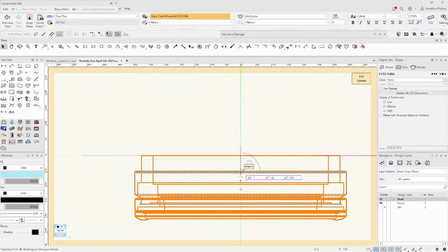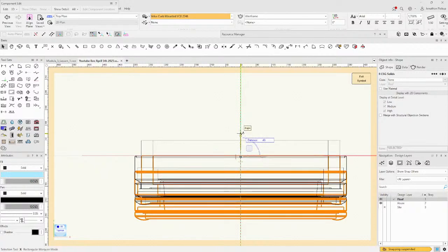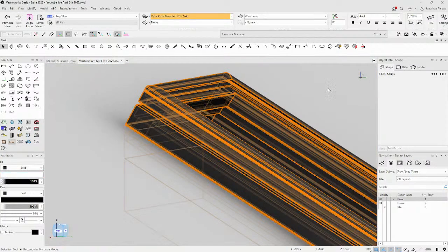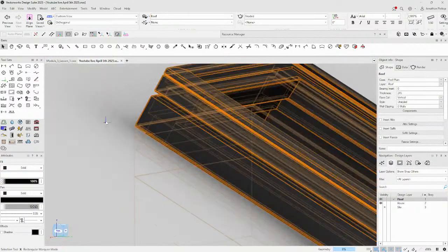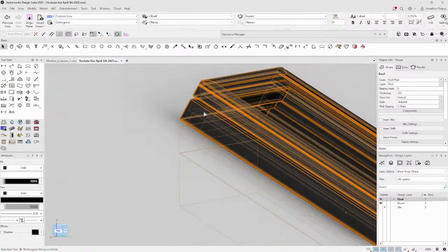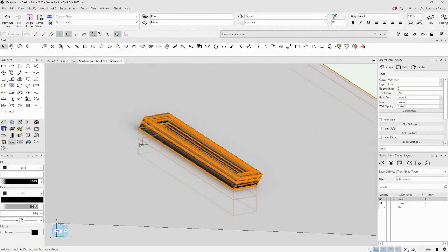I want that face. And then I'm going to go back to that where I'm going to just drag that up till it's sitting about there. Now that should make that part touch my roof. And there it is there, you can see it. What I've done is I've dropped the flange inside my roof, and so now I've got that. I tell you what, you know what this really needs is a flashing that goes around it. If I wanted to put a flashing around it, that would be extrude along a path.